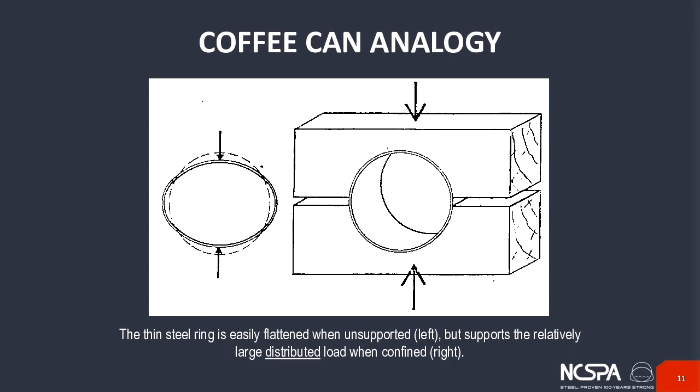And that's really what the basis of the ring compression theory and the structural design of corrugated steel pipes is all about. Having that support for the ring around it being provided by the earth embankment, and thereby allowing it to carry loads through compression in the pipe wall, as opposed to bending within the pipe wall.